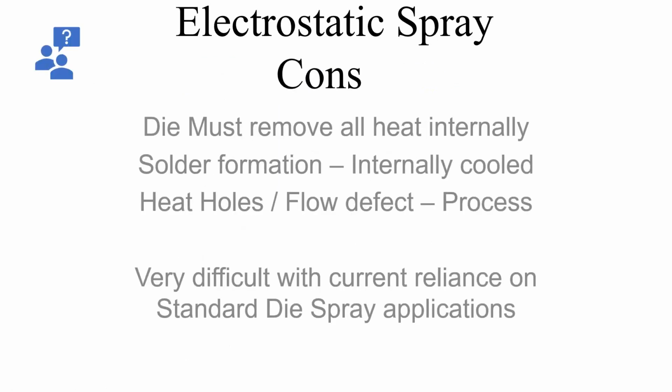Some drawbacks of electrostatic spray is that all the die heat must be removed internally. You've got to have good, engineered cooling to remove the heat from the tool. If you've got solder formation on the face of the tool, you can't just reposition a sprayer to cool that area. Electrostatic spray doesn't work that way. Once again, it's got to be internally cooled. So we could have heat holes, we could have flow defects in the process if we don't have sufficient internal cooling, or if that internal cooling is being blocked through lime or deposits in the cooling.